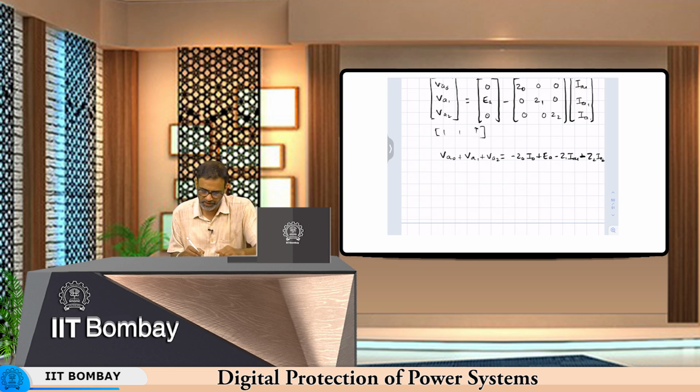Now, what is VA0 plus VA1 plus VA2? It is nothing but VA, which in this case is equal to 0, as there is a solid short to the ground. Otherwise this would be equal to ZF into IA1. But in our case we are taking it equal to 0 to simplify things a bit.